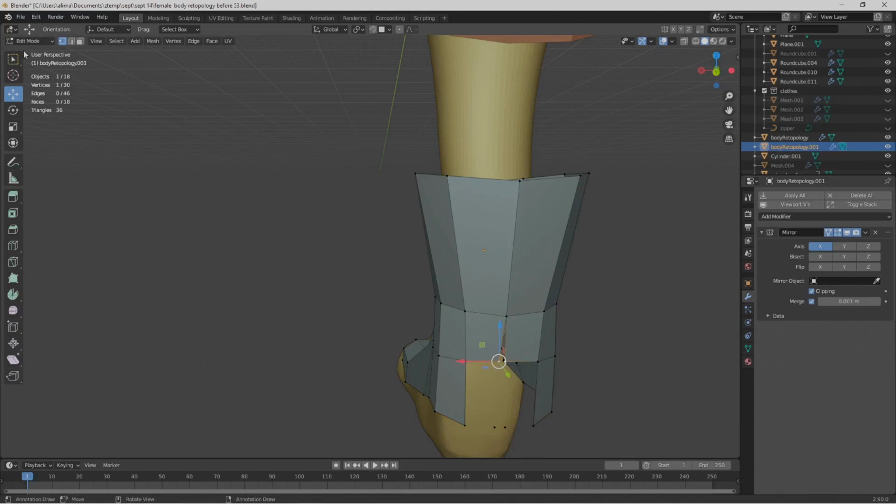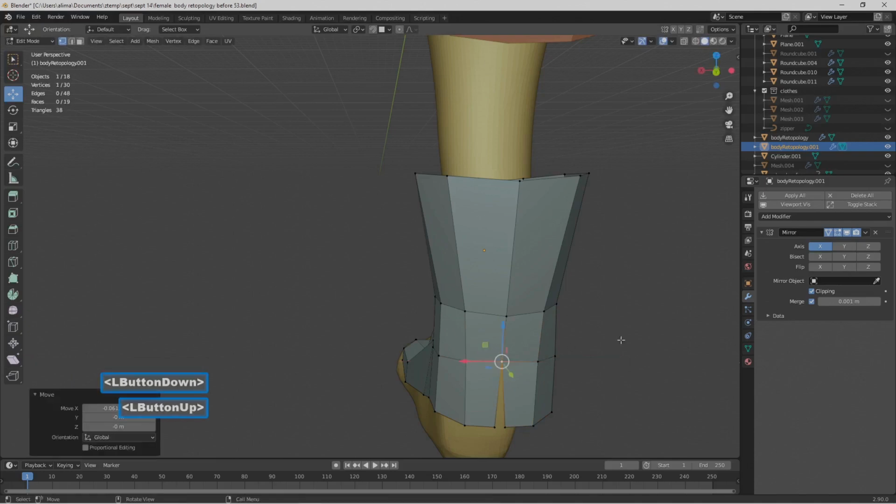This is in the way, so I'll go to the upper left to the select box. I went here just to move the manipulator out of the way. I'll hold Shift, select here as well as here. Then I'll press F to fill. I'll select here, go back to the upper left, the move tool, use the mirror modifier's clipping to have these vertices joined.